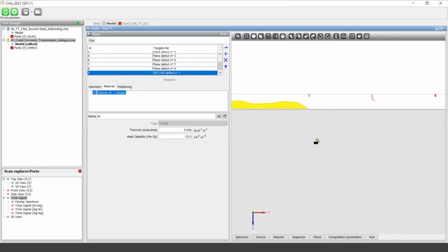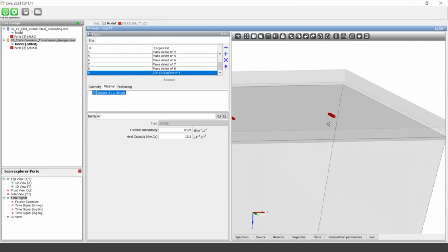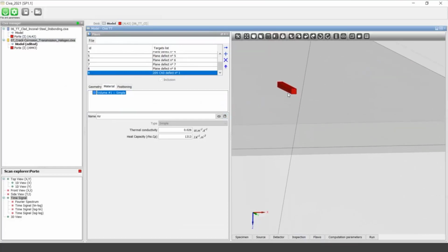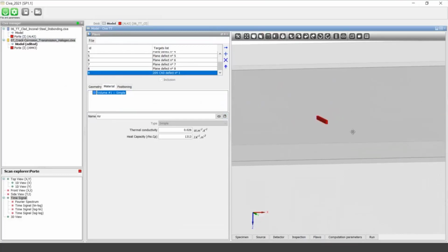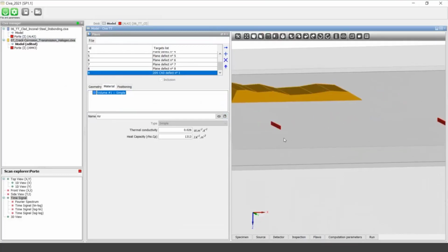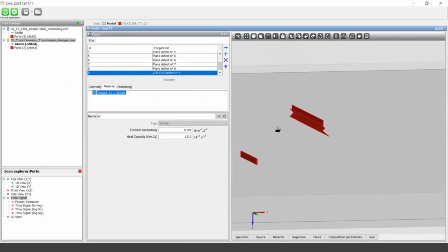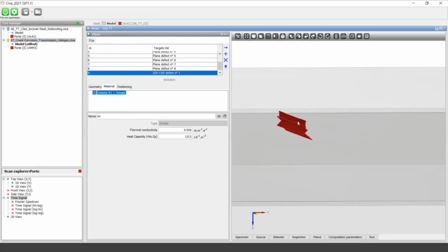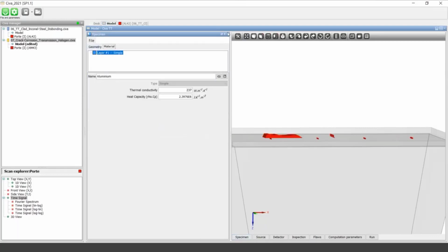So it could simulate a kind of corrosion. And on the same test piece, we have put some planar defects, but maybe here quite wide, like a big wide notch, and a smaller aperture, more like a crack. Or maybe here also we have investigated putting some planar defects to form like a branch defect in this specimen of aluminum.